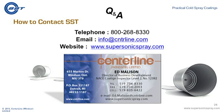One other question. It was mentioned during the webinar that the part does not need to be masked prior to spraying. How do you mitigate overspray? As far as the world of coatings is concerned, where you have a liquid particle like an organic paint or coating like a polyurethane or epoxy, or you have a melted or semi-melted particle like there is in thermal spray, those particles, if they miss the target, they will adhere to anything that's off target. And then they'll solidify either by a curing process or strictly by cooling down. In cold spray, the powder is never melted. It never sees a phase change. It always remains as a solid particle. For all intents and purposes, there is no overspray in cold spray.